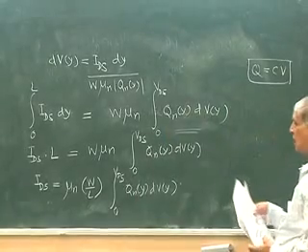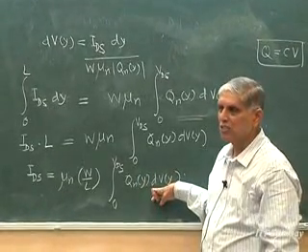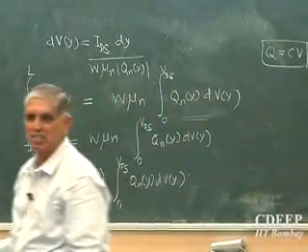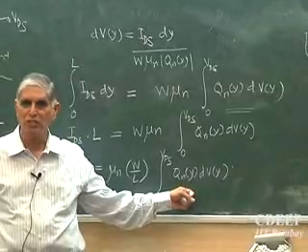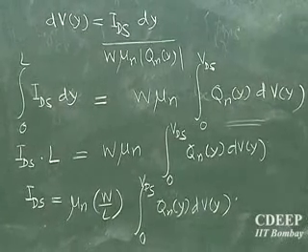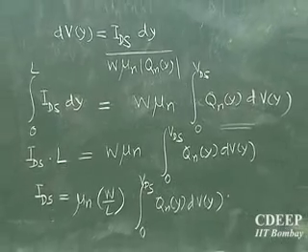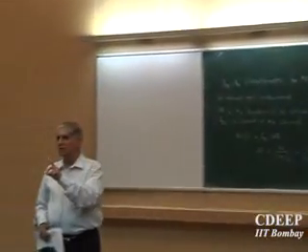Before we solve, can you now start looking, this is a VDS term, but Qn is a function of what? Inversion charge is decided by the vertical field, that is VGS. So now did you get? IDS is not only a function of VDS, but also a function of VGS. You are looking for a relationship between IDS, VDS and VGS. This equation has, if I substitute Q properly, a relationship between IDS, VGS and VDS in one go. Q and y terms will give me the VGS dependence, and the integral of voltage over length will give me the VDS dependence. So I have a current which is related to VGS, and also to VDS, or the relative values of the two. That will decide my IDS.